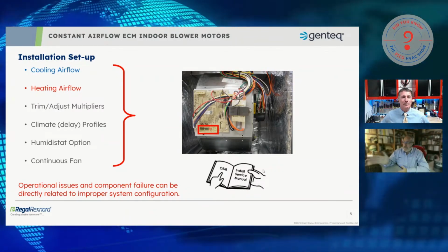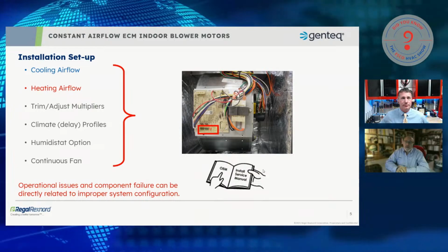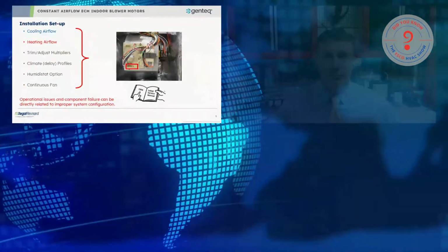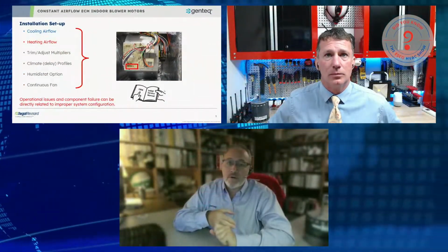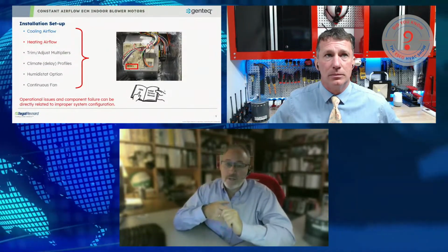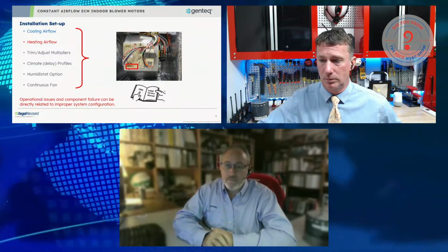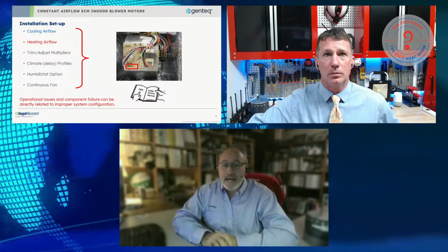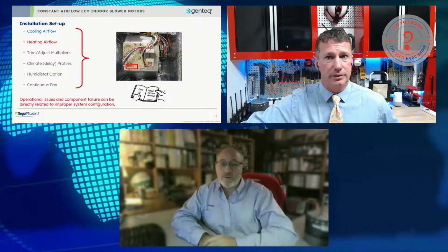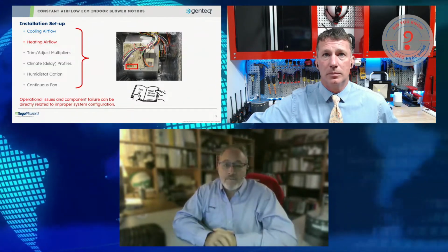But yeah, the thing to keep in mind is the cooling and heating airflow are not always going to be properly set up for every job the unit goes into, but all of those other settings, the creature comforts and the dehumidification, are going to be set at a default setting for general USA, not for a different climate, like Fargo, North Dakota compared to Miami.